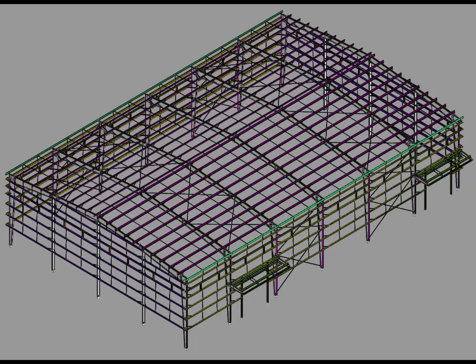So, whenever you receive a PEB project for modeling or detailing, don't immediately start modeling every member. First, study the drawings. Understand the grids. Identify the main frames. Identify the secondary framing. Locate the bracing. Locate the sag rods. And then use the 3D model or your developing model to continuously verify the arrangement.